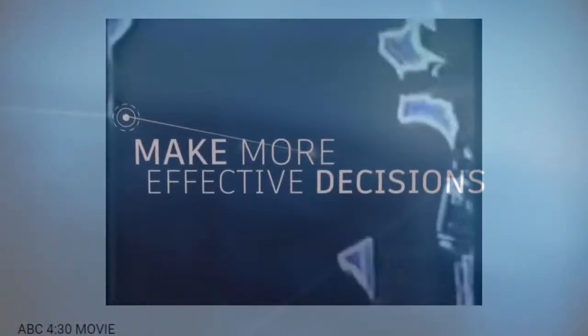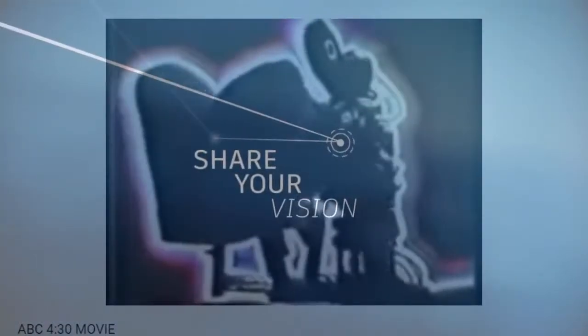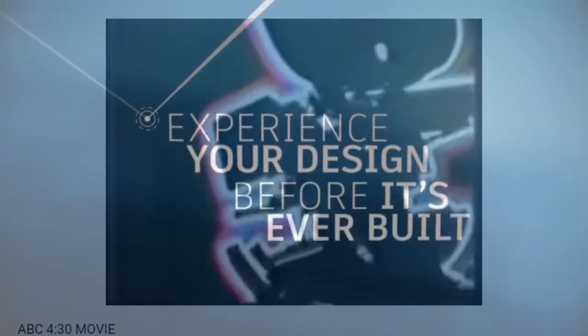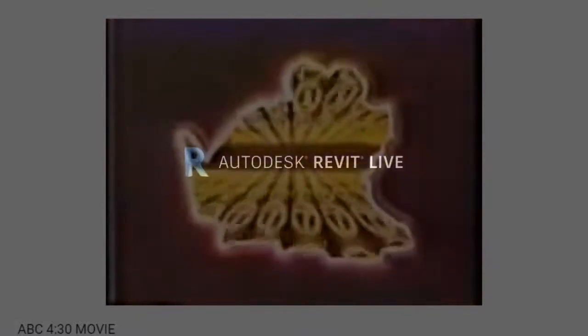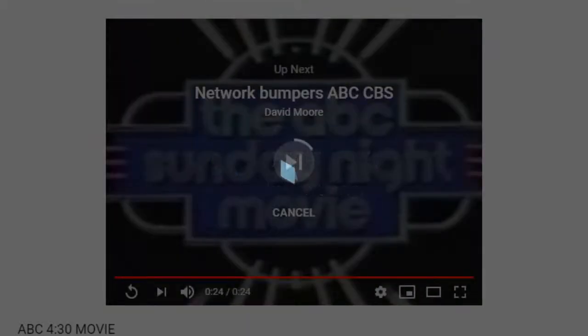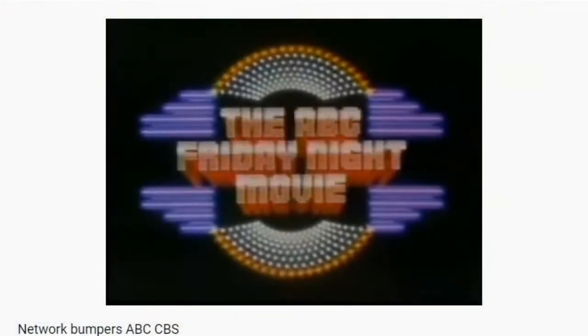We need to add small areas of thick floor finishes. You may encounter one of two scenarios, with a depressed floor and without. In areas such as bathrooms, a thick set tile floor may require the structural slab to be depressed in order to accommodate the thickness of the finished material. The main floor object in this figure is going to be cut with an opening at the inside face of the walls. Another floor is modeled with a negative offset value to accommodate the thickness of the tile material, and the tile is in place as a main floor element.